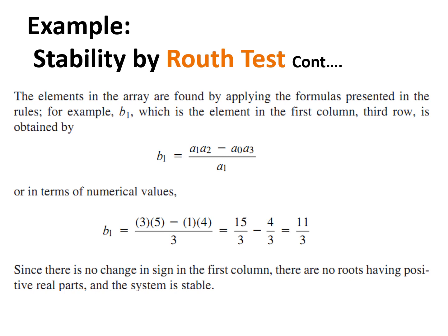Stability can be affected by the tuning constants, and this method can also be used to get the right tuning, normally just for the KC. What is the KC that will give stability? Stability means what KC will give a first column that is all positive. It's possible this way.